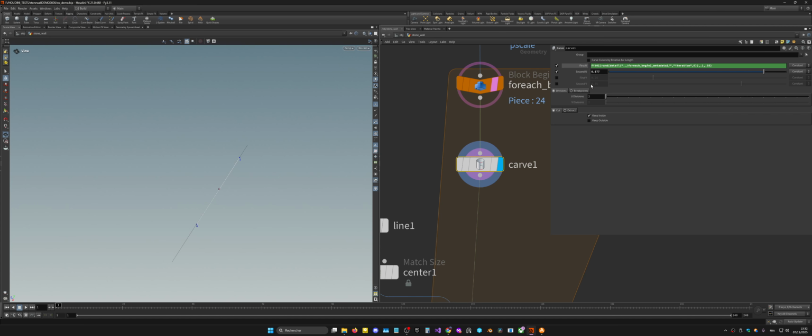So copy parameter, I right click on first U, I choose copy parameter, and in second U I type 1.0, that is the maximum, minus, and then I paste with special, that is right click, paste parameter, relative references, and now it pastes the link to this value. So it's the same, inverted, as you can see.